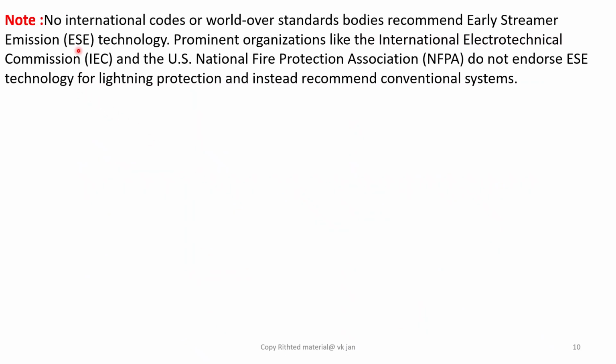Friends, no international code or worldwide standard body recommends early streamer emission technology. Prominent organizations like the International Electrotechnical Commission (IEC) and the US National Fire Protection Association (NFPA) don't endorse ESE technology for lightning protection, and instead they recommend conventional systems. Only a few countries are using ESE.